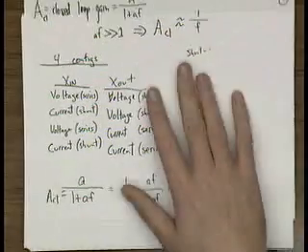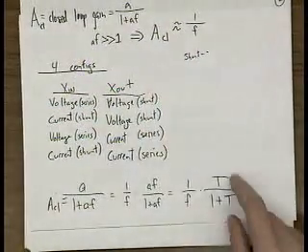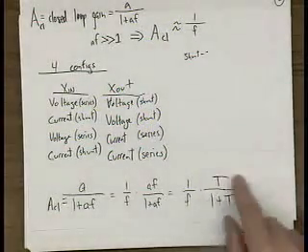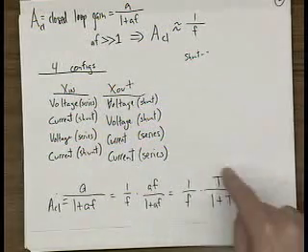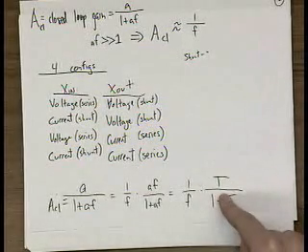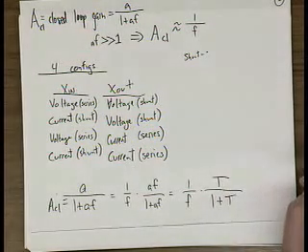Before I said A closed loop approximately equals 1 over F, but it doesn't quite equal 1 over F. You have some loss, since T over 1 plus T is going to be less than 1, obviously. So you have some loss mechanism here due to non-infinite loop gain, but you can quantify exactly what that loss is.